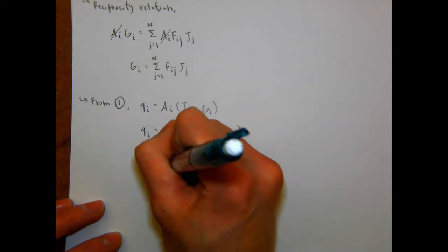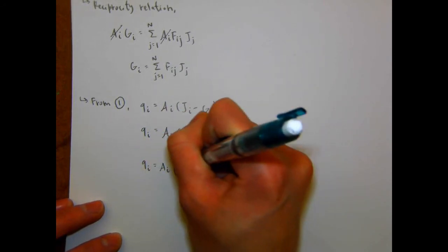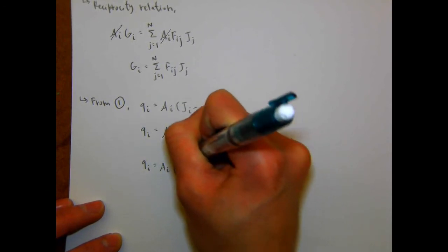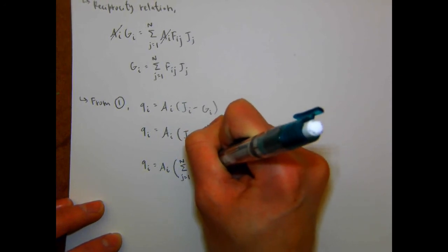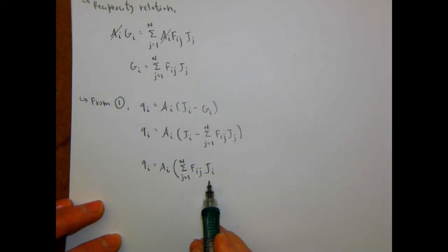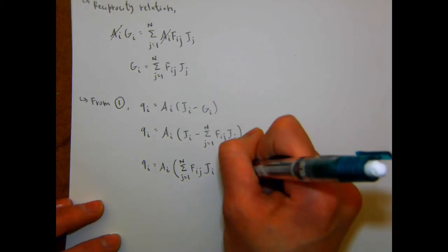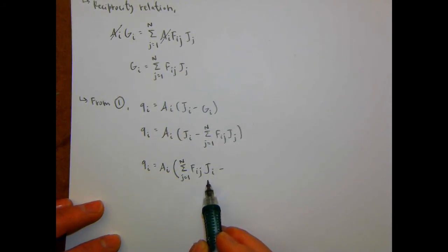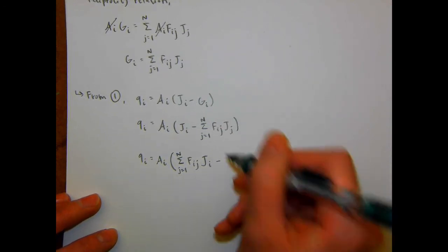And we can use the summation rule to rewrite this. So we know the sum of the view factors for all the surfaces in an enclosure is equal to 1. So we can basically just write this in front of the radiosity, where it's like a multiplication by 1. And again, we're summing over J. So the radiosity of the surface I is a constant, so we're not bringing this into the summation. It's just multiplying by a factor of 1.